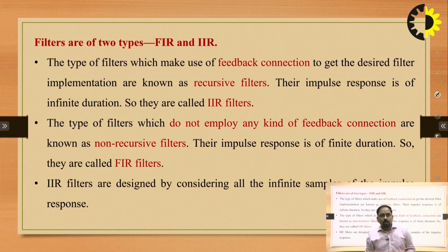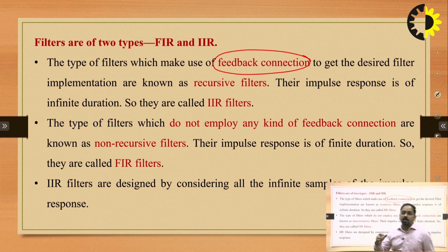Now we have the types of filters. Filters are classified on the basis of their impulse response, as FIR and IIR. First of all, we will see the type of filter which makes use of feedback connections. If some part of the output is fed back to the input side, those types of filters are called recursive filters, and the impulse response of these types of filters is of infinite duration.